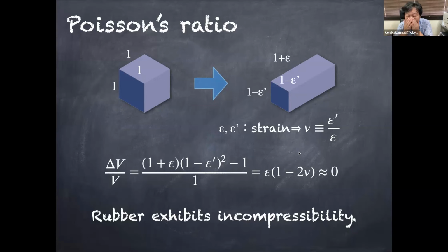Mass doesn't change, which means that the density decreases. Why does density decrease? Uniformly? Maybe not. There would be a hole, a void in it. A stretched sample may contain many voids inside. That's the reason the volume change becomes positive.